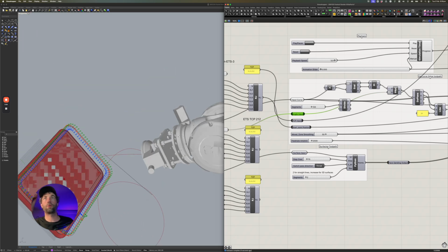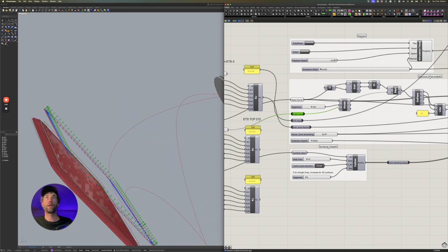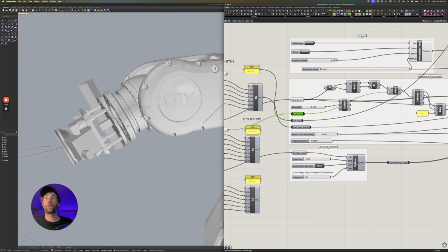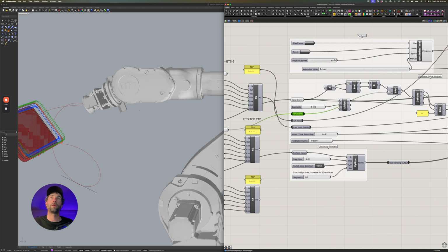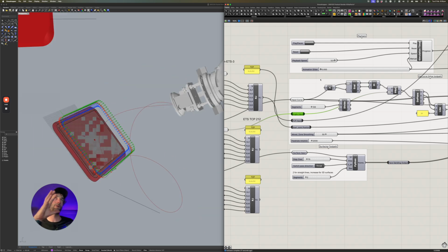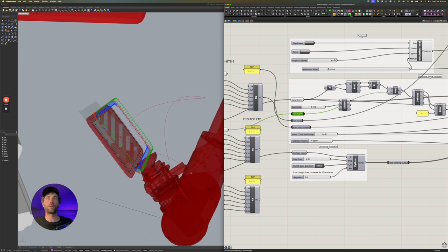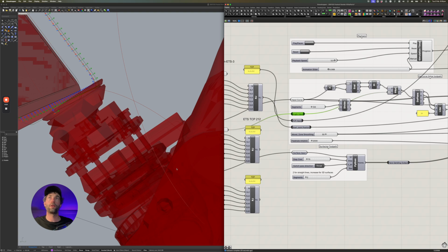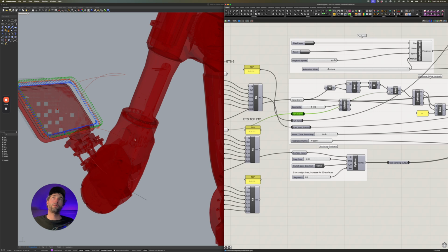And since I rebuilt this with a little air glide Festool rig, which is working beautifully for consistent pressure, really happy with that, it means the tool is longer in Z, and now I've actually got a joint 5 clash. When it comes down here, it gets bound up too tight in joint 5. So I need to work out what to do about that.